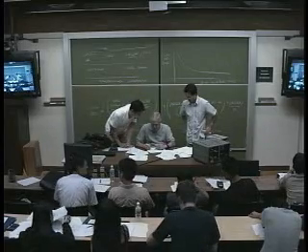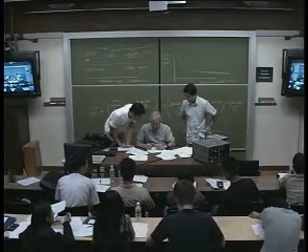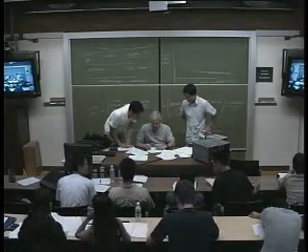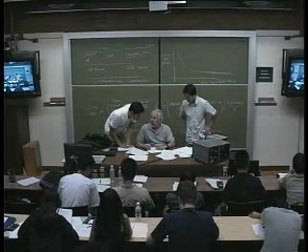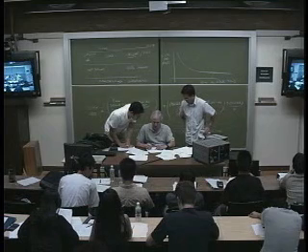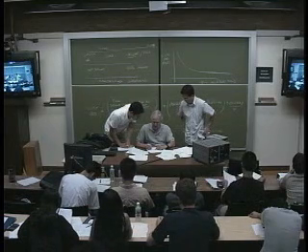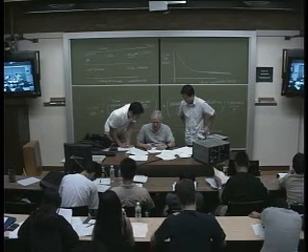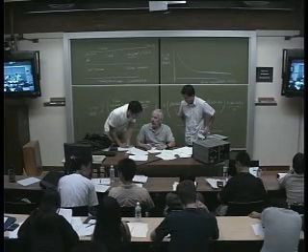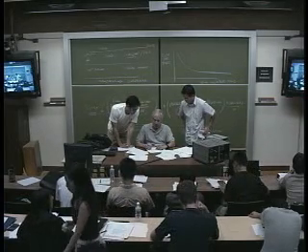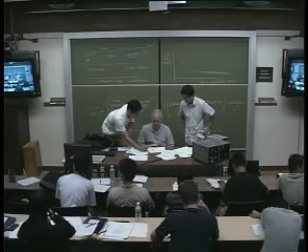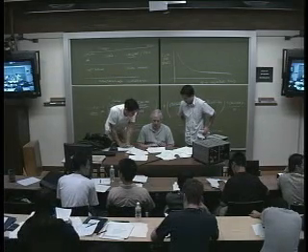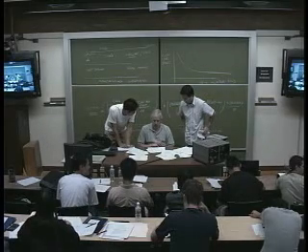Well, look at it. This current here equals this current, right? Okay. So tying this to here is almost the same as tying it to there, right? Because the current through here is the same. So that's like a diode connected transistor, right? Oh, yeah. But I'm putting it up here, so it does double duty. Is it 1 over GM3 plus 1 over GM5 then? Or 1 over GM3 plus GM5?